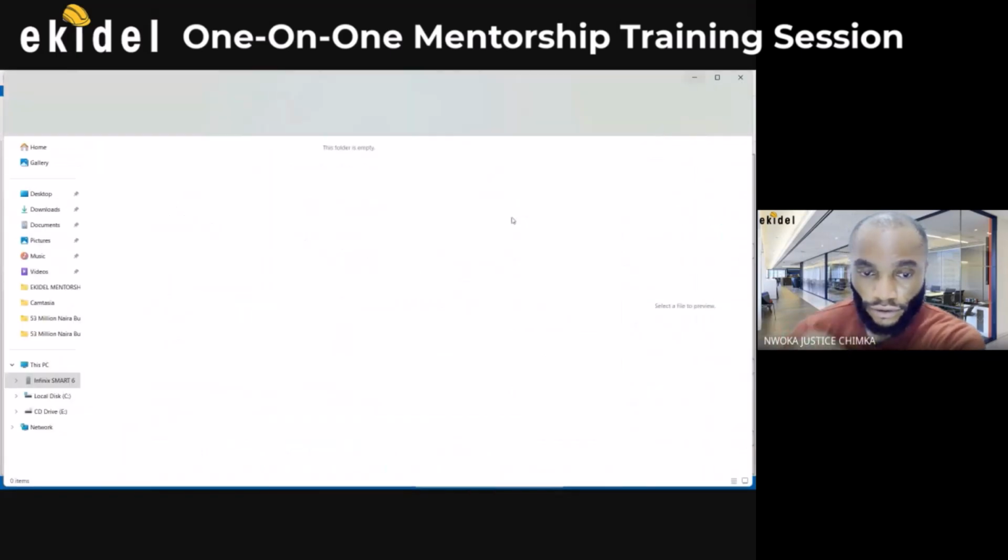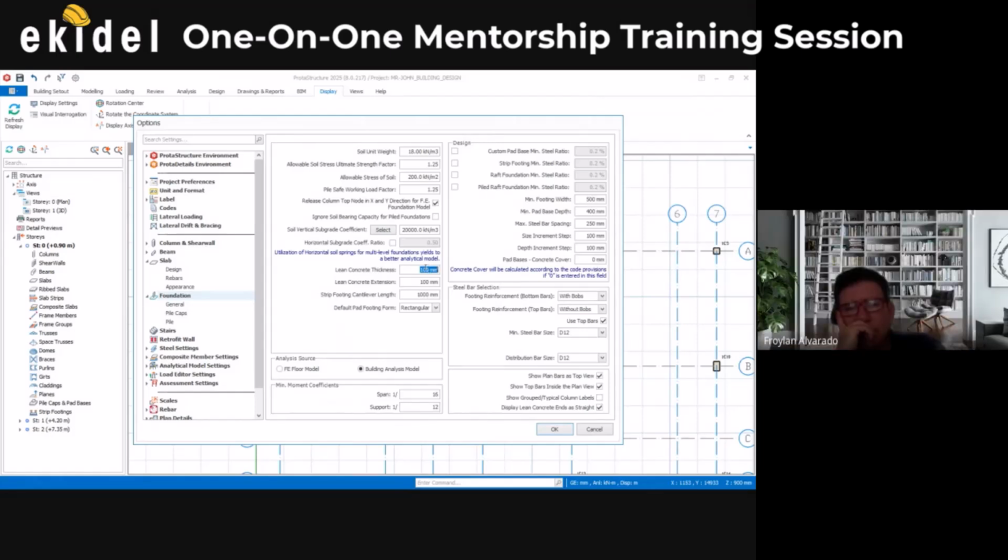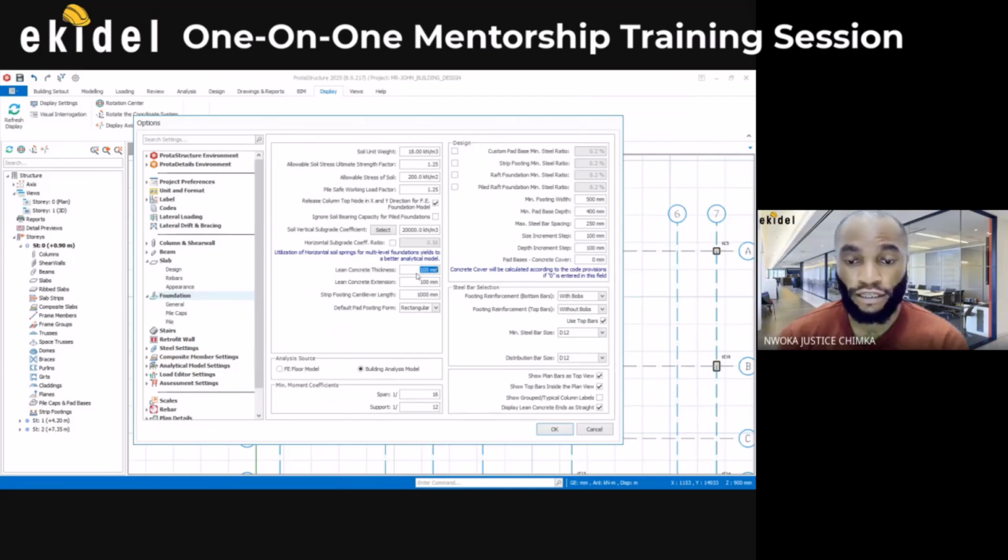Then we move to, I think that's all for settings here. These other ones are for lean concrete. I think for lean concrete you can either use 75 or 100, but in my country here, we use 50 as the minimum. But based on ACI, they say 75 and all that. So either 75 or 100 for lean concrete. Yeah, so let me say 75. Then extension, same thing, 75 or 100.